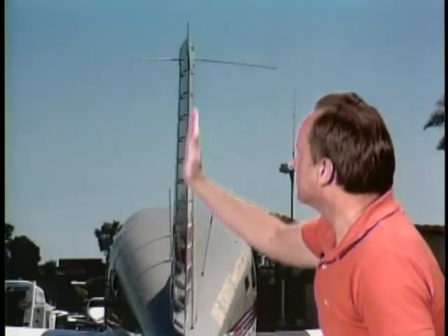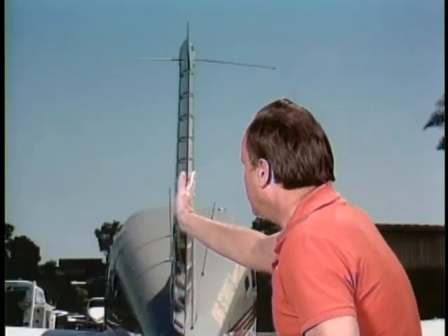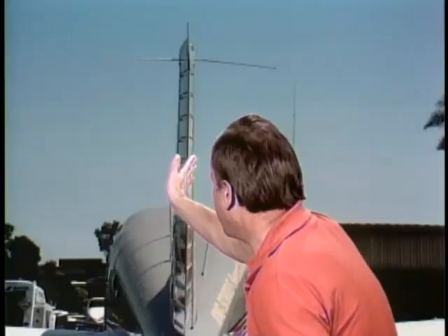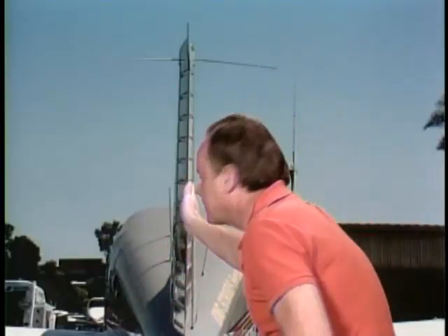And if the vertical tail of a single-engine, propeller-driven airplane is rigged properly, it will generally be, according to the FAA, parallel to the vertical axis. In other words, it'll be right straight up. But it will not be parallel to the longitudinal axis because you need to have a little bit of an angle there so you can correct for the natural left turning tendency of the aircraft. So if a vertical fin of a single-engine, propeller-driven airplane is rigged properly, it will generally be parallel to the vertical axis, but not to the longitudinal axis of the airplane.